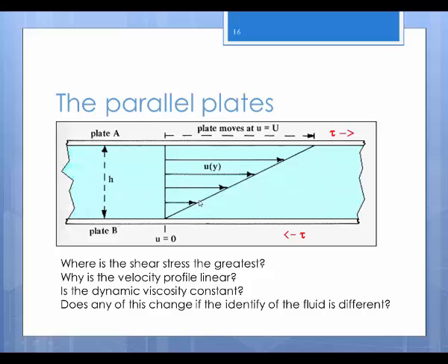Right up at the top, at the bottom here. And then at the top, this fluid is at u, say like 1 meter per second or something. Then the fluid at the top that's in contact with it is exactly 1 meter per second. It tracks right along with the plate moving. It doesn't slip. If it slipped, it could have a velocity that's different from the solid boundary that it's in contact with. But since it doesn't, that's the no-slip condition.